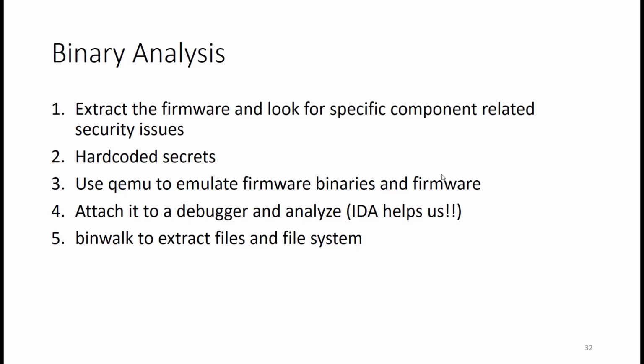So through the dump, we can extract the firmware, we can find out the specific required information from the binary, we can find out the hard-coded secrets like passwords, credentials, keys. We might also need to emulate the firmware to understand how the functions of the embedded device are working.